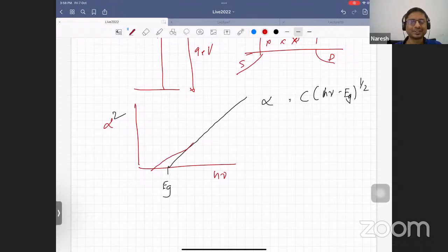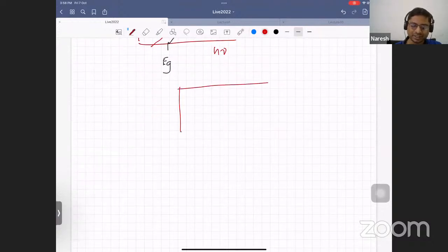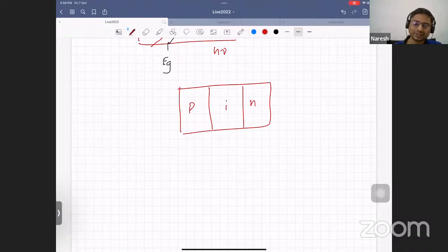So we actually use, sorry, give me a minute. We talk about PIN diodes. Remember, in the photodetectors part, I talked about this, wherein I have this, and this is intrinsic. This is undoped. The reason for that is a little bit more complex. What I'm saying essentially is that you have the highest generation rate when you have this carrier density.